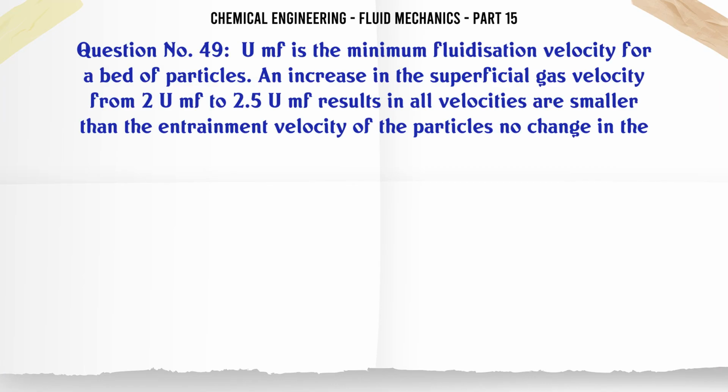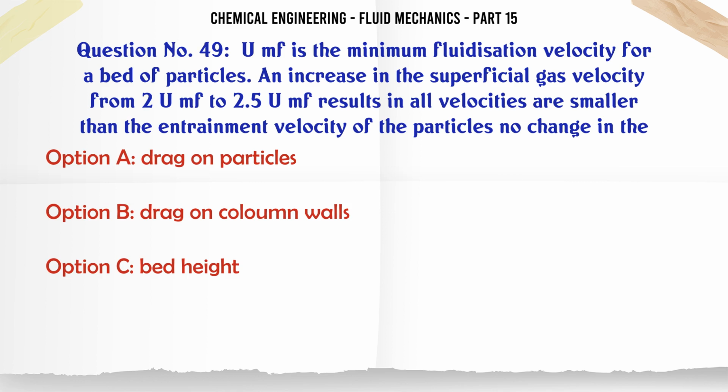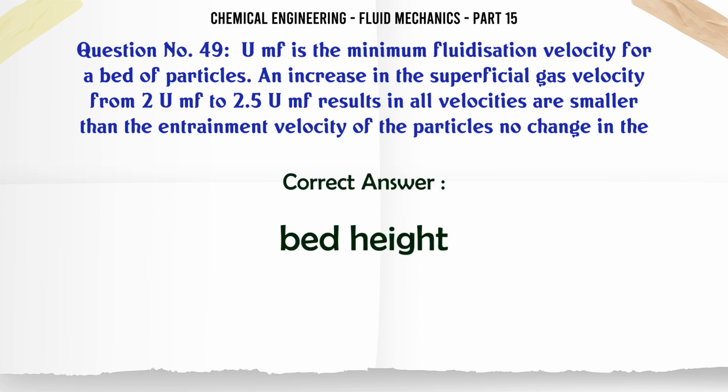UMF is the minimum fluidization velocity for a bed of particles. An increase in the superficial gas velocity from 2 UMF to 2.5 UMF, where all velocities are smaller than the entrainment velocity of the particles, results in no change in the A. drag on particles, B. drag on column walls, C. bed height, D. bed voidage. The correct answer is bed height.